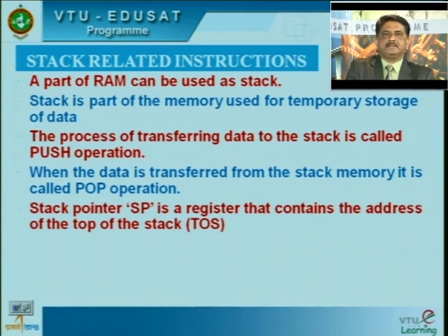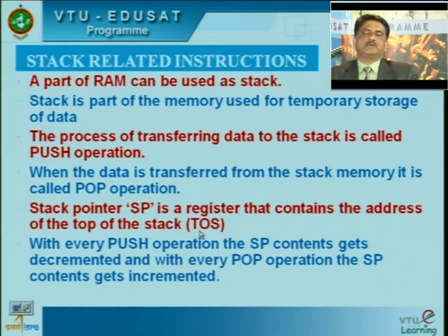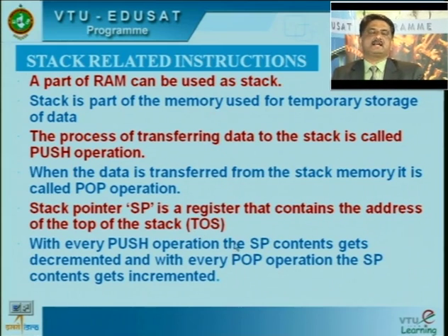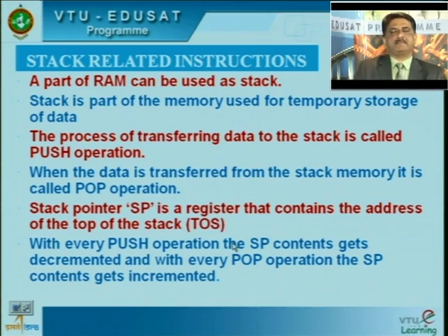The stack pointer is a 16-bit register which we have discussed in the architecture of the 8086, present in the register set of the 8086. SP will always point to the top of the stack. It is a 16-bit register which only works with the stack segment. With every push operation, the SP contents get decremented by 2, and for every pop operation, the SP contents get incremented by 2.